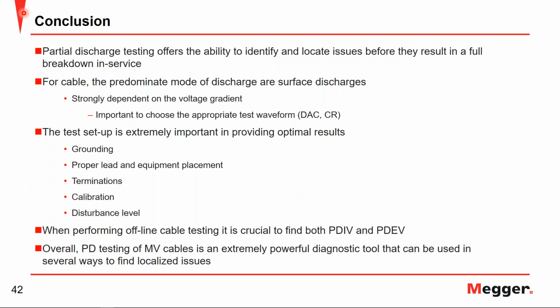Overall, partial discharge testing on medium voltage cables is an extremely powerful diagnostic tool and can be used in several different ways, as we talked about with damped AC or cosine rectangular, to find localized issues or defects within your cable.